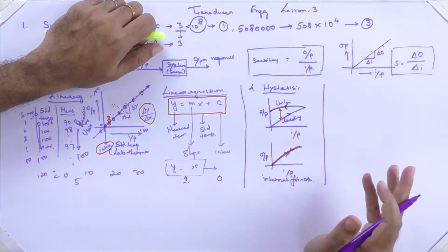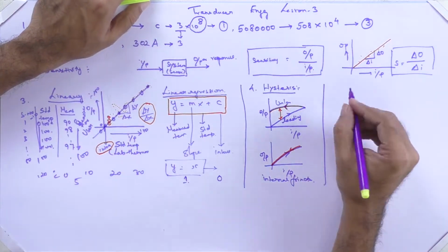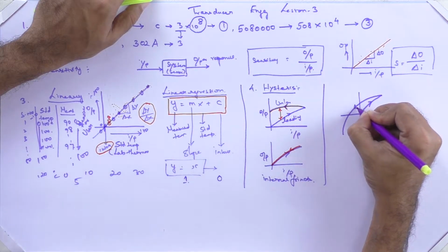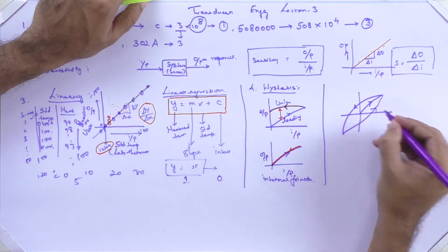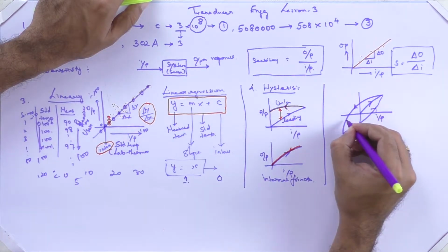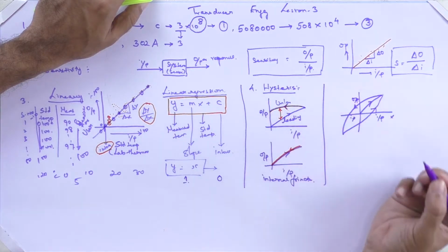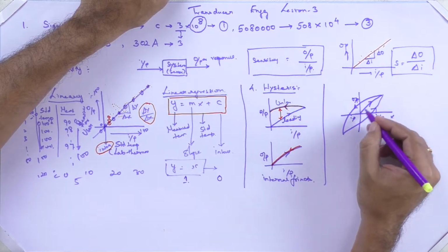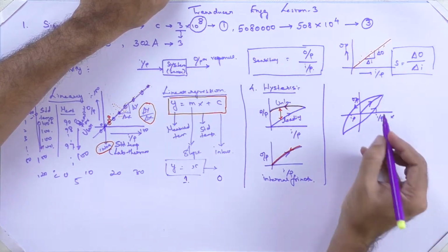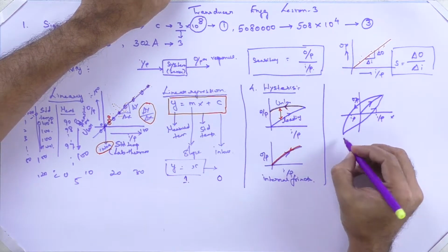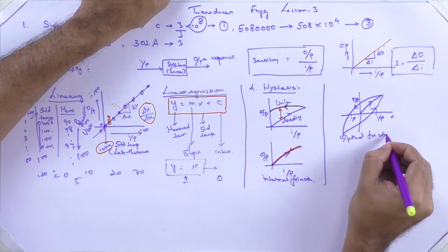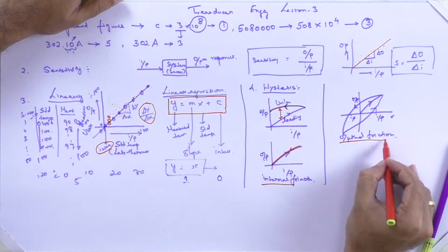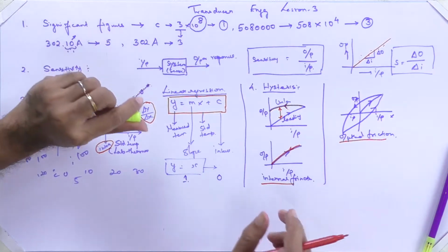If you take the outside frictional motors and other kinds of equipment, the hysteresis loop will look like this. You are giving a loading, unloading, and again when you load, it will look typically in this shape. This x-axis is input, this is output. So this is loading, this is the unloading. Again when you load it, nothing will occur in the same fashion as it occurred before. So this is one kind of loop, and this is because of the outside friction. Now we are very clear about hysteresis problems. One is because of internal friction, then outside friction, and magnetic effects also produce these kinds of hysteresis effects.